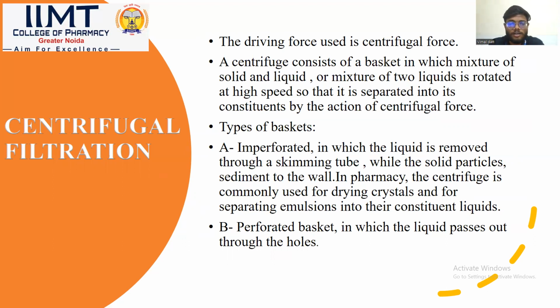Type of basket. Type A basket is imperforated, in which the liquid is removed through a skimming tube while the solid particles sediment to the wall. In pharmacy, the centrifuge is commonly used for drying crystals and for separating emulsions into their constituent liquids.